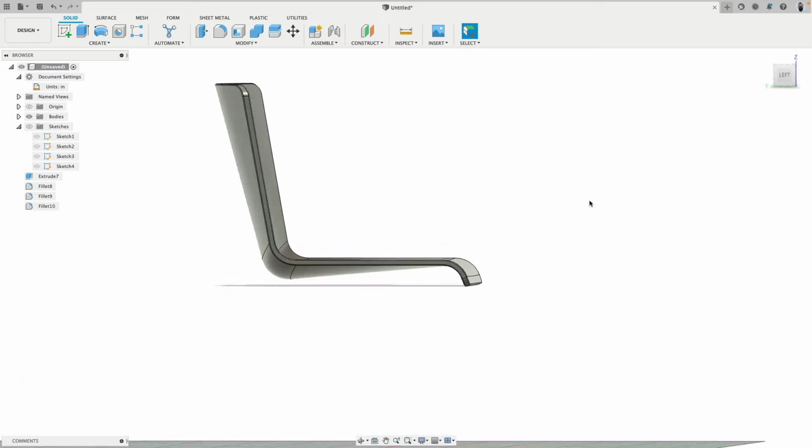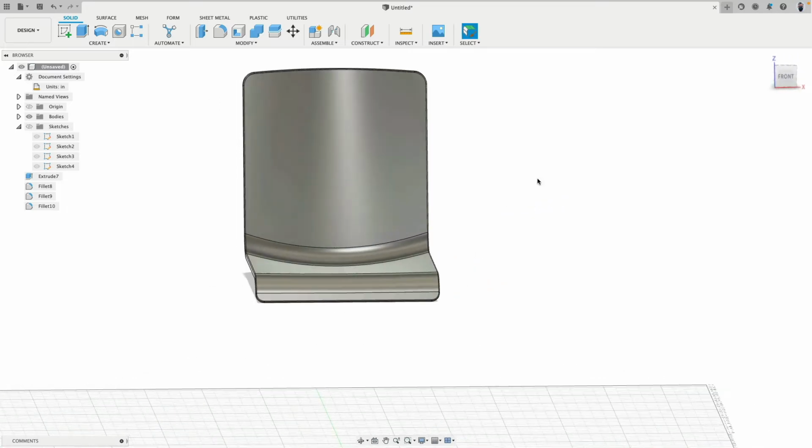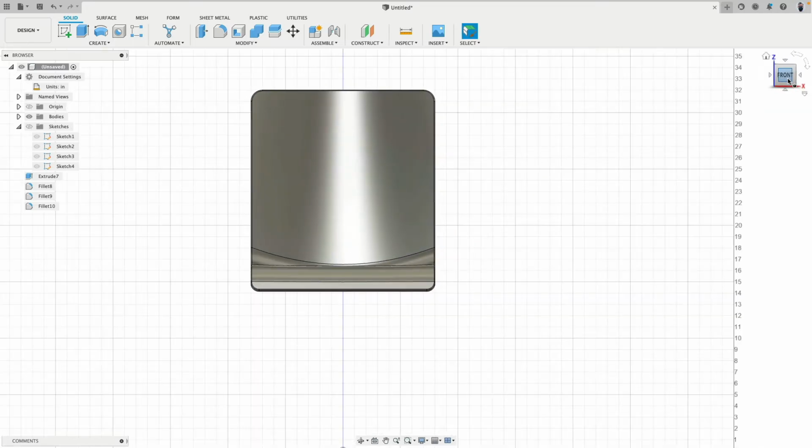Okay, very good, no? Because if you make such a piece out of bent plywood and you take it over the press, then we can run it across a bandsaw and then a sander and clean everything up. And this is kind of like what I did here. Specifically with furniture, when I design a product for a client, I really use the methods in the prototyping woodshop in guiding me how to design this in Fusion. Because in the end, they will have to do this with their materials anyway. So this is actually a really huge helper to just model it with physical machines and processes in mind.